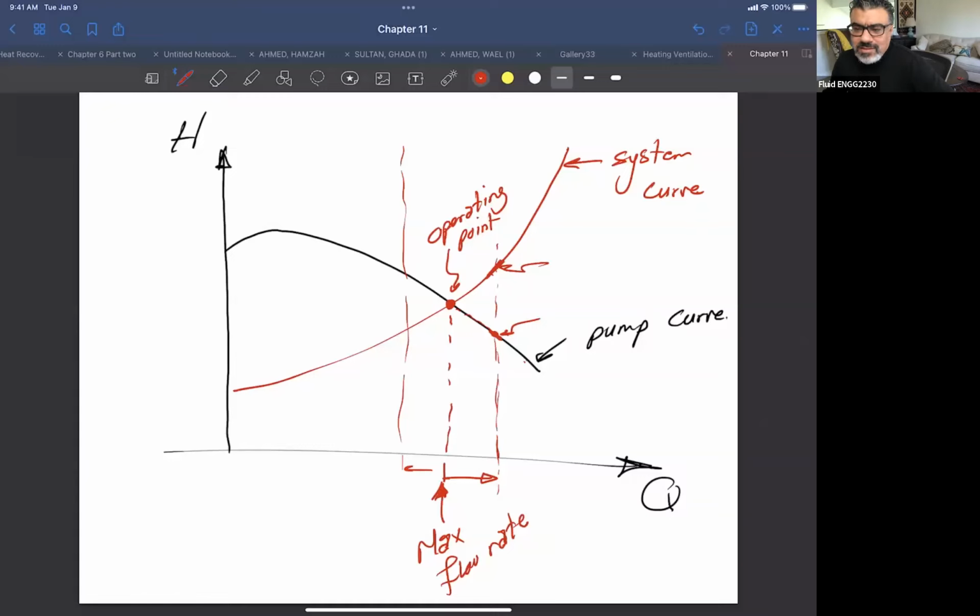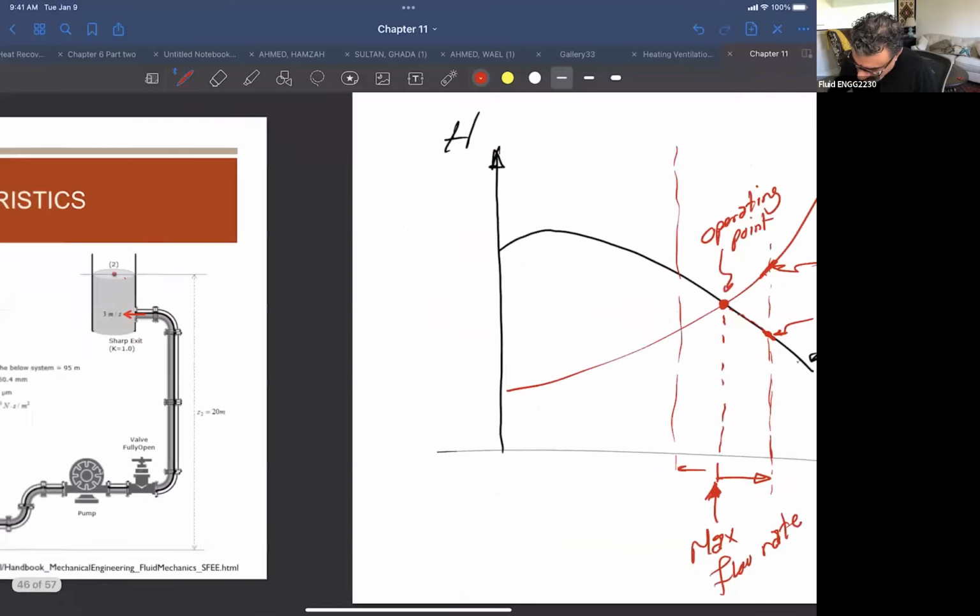Simply think simple, okay, guys. It's not very complicated. How are you going to decrease the flow rate if you open the tap in the morning? Use a valve, right? Just close the valve at the exit a little bit. By closing the valve, you are increasing the losses, actually. You are changing the system, because this system, you remember, is a function of K, right?